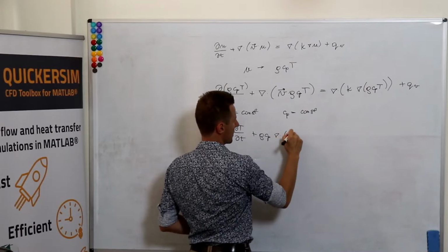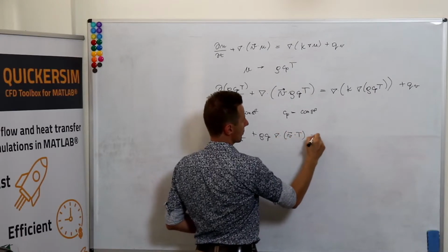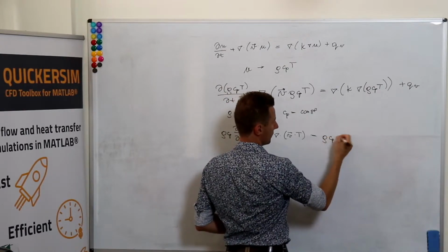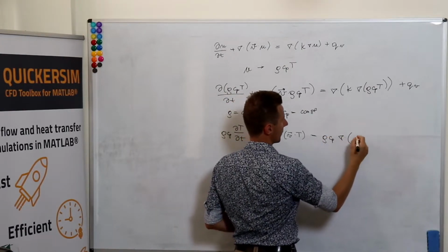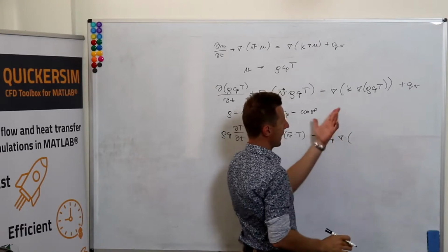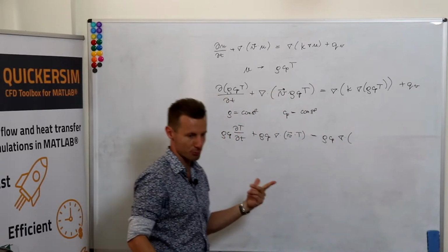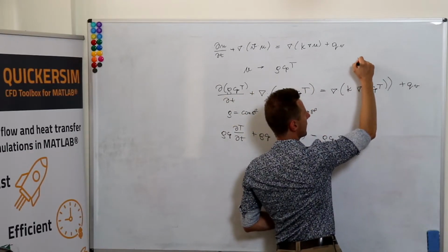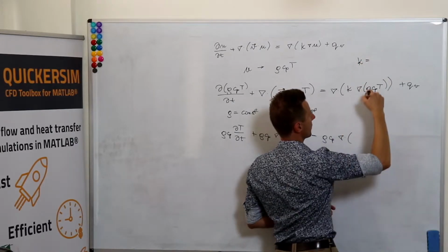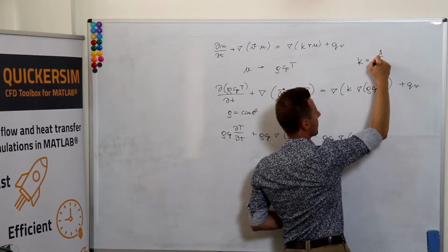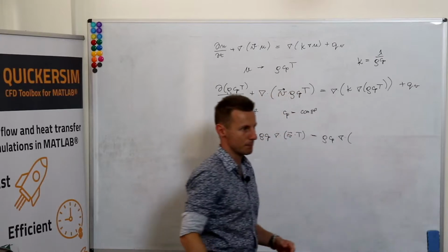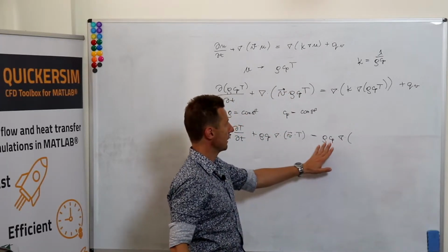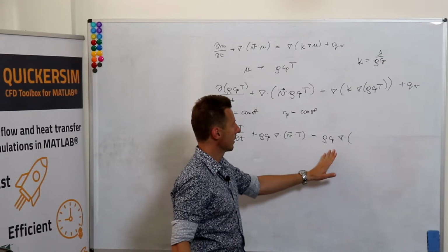Divergence of the velocity times temperature equals, basically, let me write it this way. And as we have mentioned recently, you remember I have been defining K or A, whatever it should be, as lambda divided by Cp, divided by rho Cp. So if we take it out, then